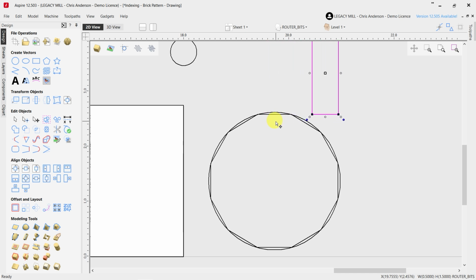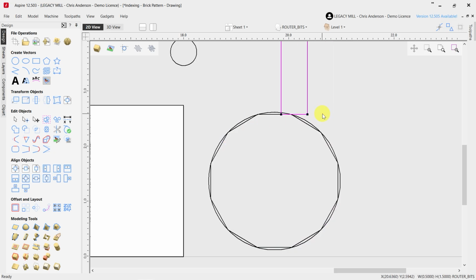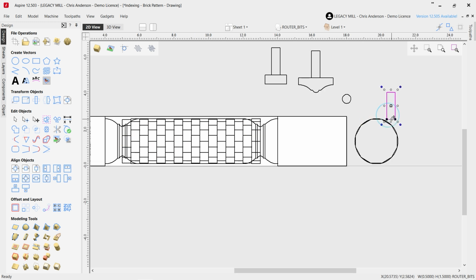And then after it's got to that cut depth, it's going to then cut across the part and then cut all the way back. And then it's going to take our blank and index it to the next flat section area. And the cutter will just repeat that process, cutting all the way back, and cut again and again until it applies the flats around the circumference at that single location along the x-axis. And so that shows better over here.